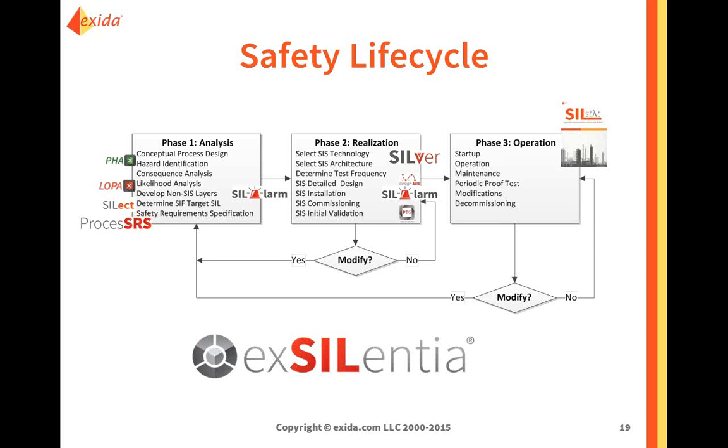And then during operation, we have our SILstat software, our live event recording software, that you can use to record proof tests, to record failures, to record demands, and so on, and successive failure of layers of protection. Information, obviously, that you want to collect to eventually feed into your layer of protection analysis. The actual alarm rationalization work tends to be done as part of the analysis and realization phase. The alarm tool also works in the operation phase as an audit tool to make sure that the alarms haven't been modified. So you could put it in the operation phase here as well.